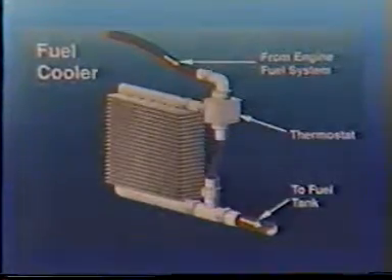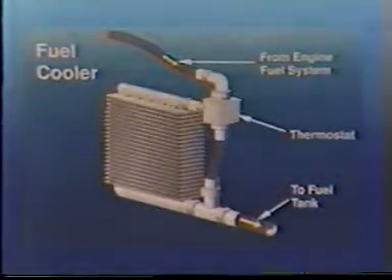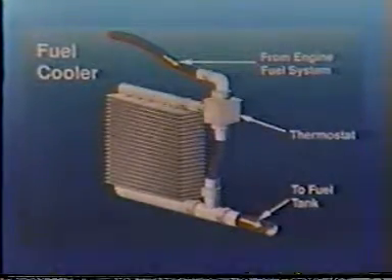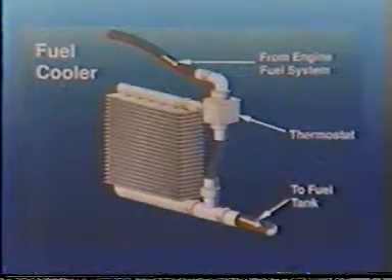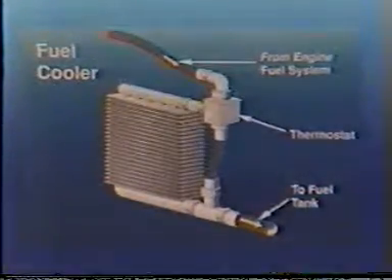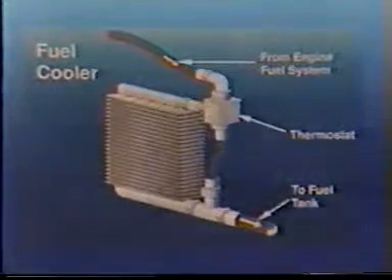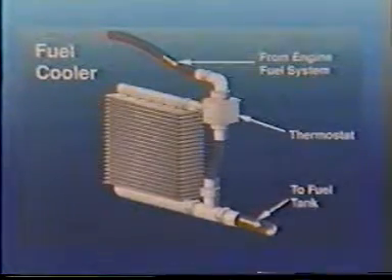Although heat is dissipated from the fuel by the supply tank, the use of the fuel cooler ensures positive temperature control. The typical drain fuel flow rate is 2 gallons per minute. Also, the cooling radiator can have no more than a 5 psi restriction.